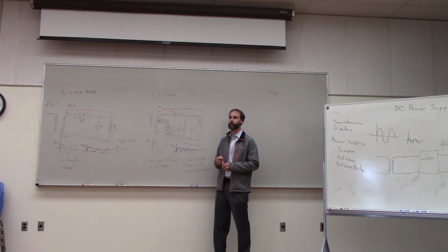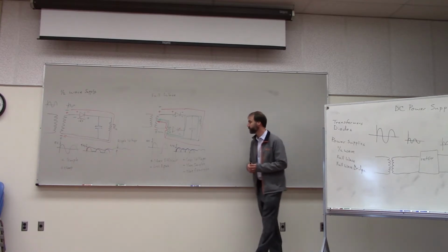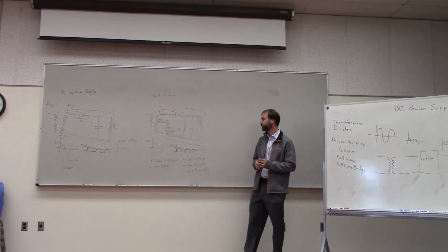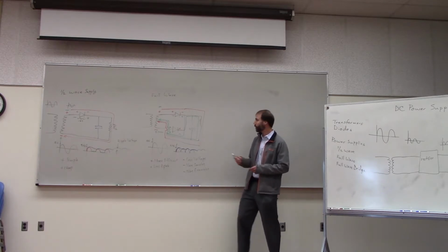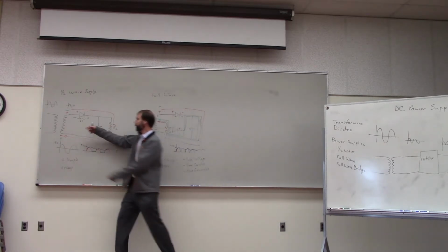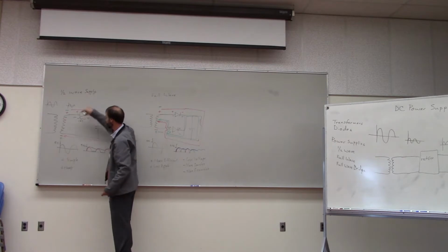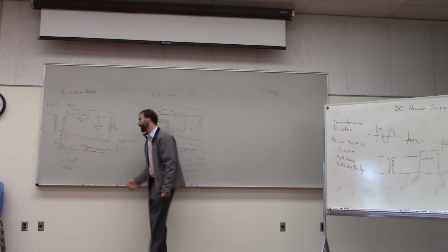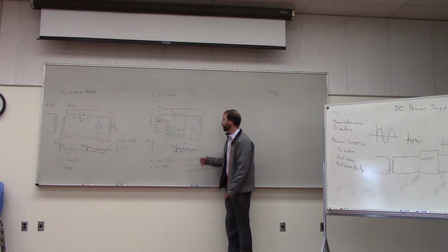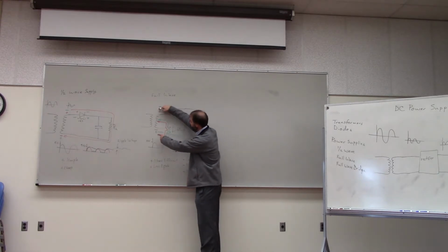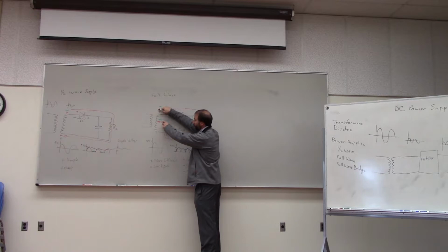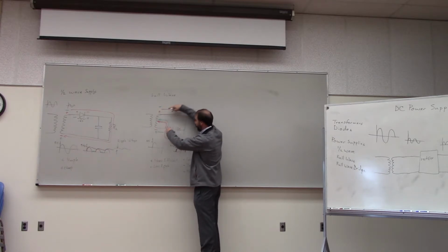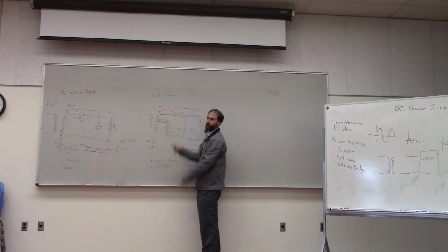Yeah. You said low voltage, so that means you could put like low voltage in the halfway? Yeah. Remember, coming out of here, we started with 10 volts and we lost 0.6, so we got a peak voltage of 9.4 coming out. Over here, we have 10 volts from the top of the transformer to the bottom, but we're using this CenterTap transformer, so we're going to the center each time, so we're really only starting off with 5 volts there.